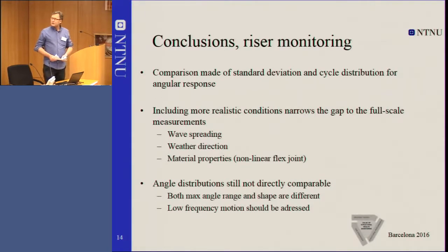But we also see that the low frequency motion should be addressed to have a better prediction of the very high amplitude but very few cycles. But when it comes to fatigue, what really contributes is mainly the intermediate range, because we have multiple cycles at that range, and the low cycle, high amplitude cycles do not give so high contributions to the fatigue for the present S-N curve that we are applying.